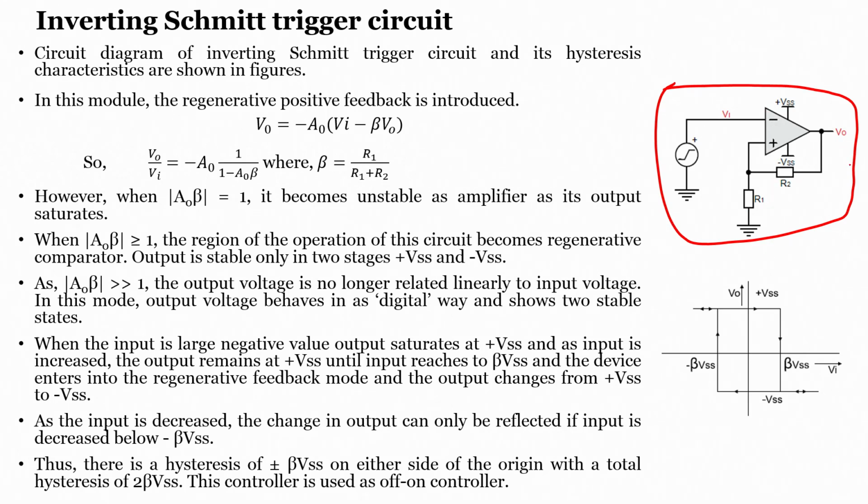That is called negative feedback, whereas in a Schmitt trigger the feedback is positive. As we know, the op amp open loop gain itself is very high, and when you connect positive feedback, the overall gain of the system becomes even higher, as we have already seen in the class. That is the reason the op amp will always be in saturation.